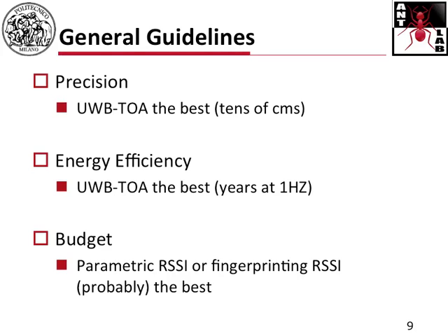Parametric means that you extract the distance information based on a parametric model. So you assume that the received power behaves with a given law with respect to the distance traveled by the signal. In non-parametric models, which are also called fingerprinting-based models, you just site survey your environment and then you extract the information on the distance just by querying a database which you pre-filled beforehand. Okay?